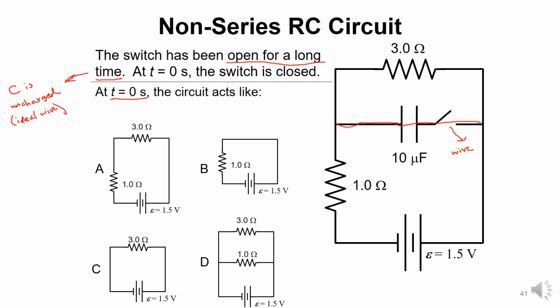The lower branch has a wire that has 0 resistance, and the upper branch has some non-zero resistance. We know that if you have 2 branches, one with 0 resistance and the other with non-zero resistance, the entire current flows through the one with 0 resistance, and there is no current flowing to the other branch.